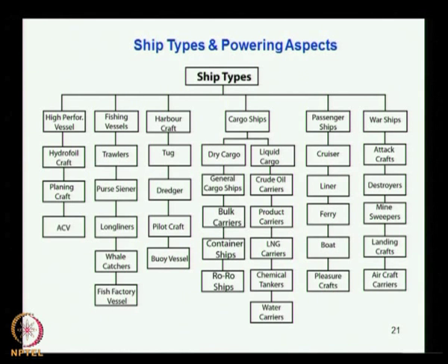And this being the case, the hull has gone up, then the resistance comes down because now it is air resistance primarily, and reduced resistance results in higher speed. So this type of vessel, being above water, usually uses air propellers, not water propellers. So that is the air cushion vehicle.